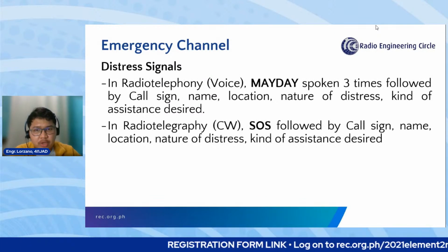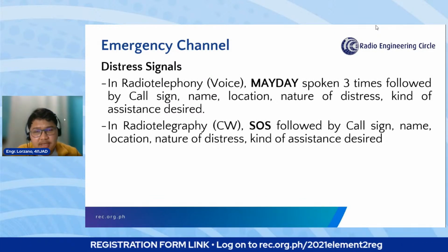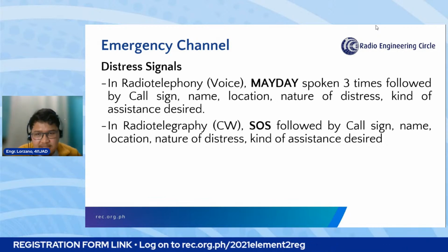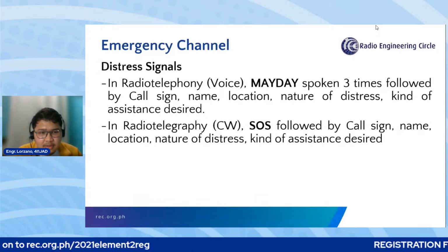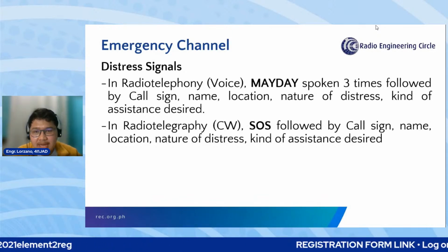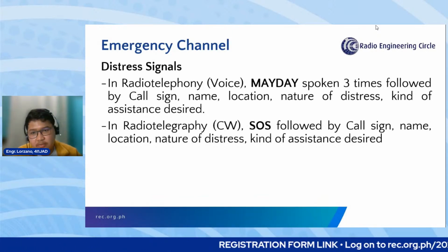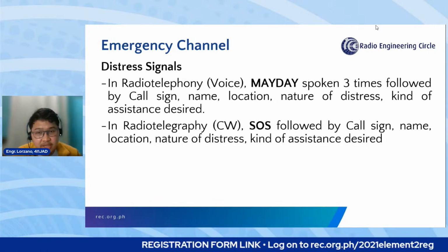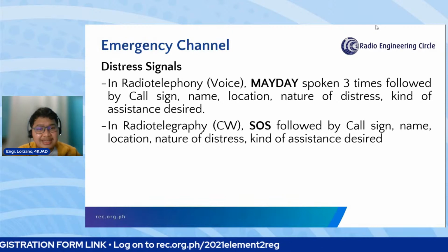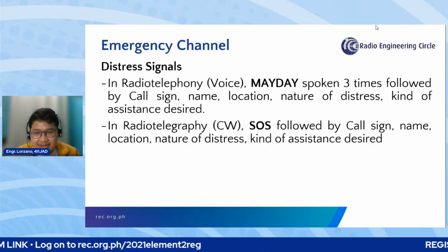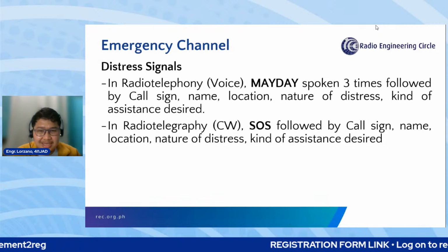So here in emergency channel, yung mga distress signals, pwede nating isend through the following. In radio telephony or using our voice, Mayday spoken 3 times, followed by call sign, name, location, nature of distress, and kind of assistance desired.